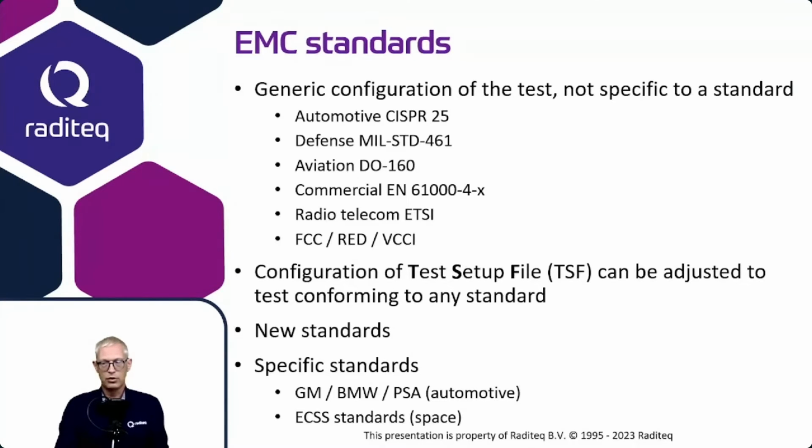By setting the correct start and stop frequency, the modulation type, and the carrier level, the test can be configured to comply to every standard. So we fully support the automotive CISPR 25 test, we support the MIL standard test, we support the DO-160 testing. All these tests are supported, and they can be easily supported by just setting the correct settings in the test setup file according to what's required by the standard.